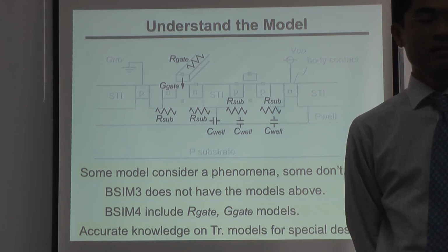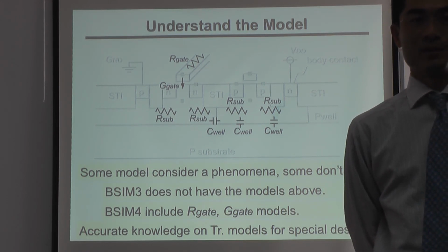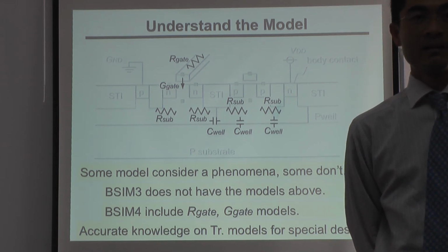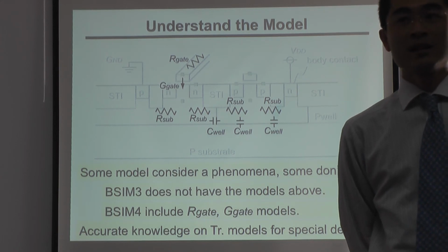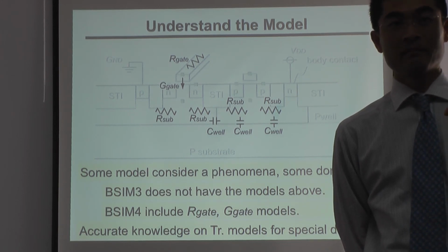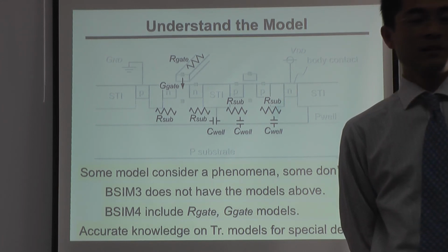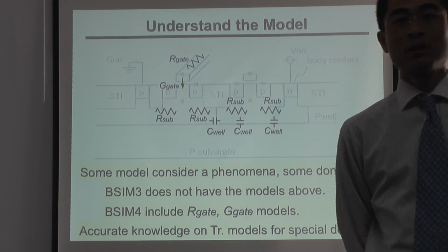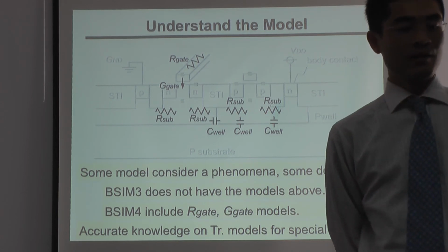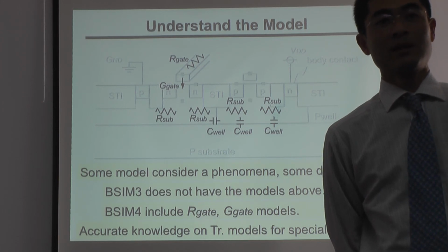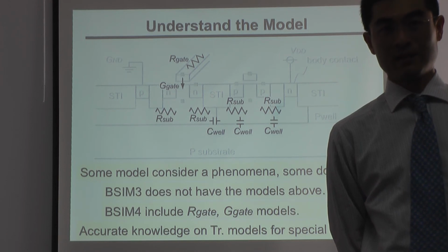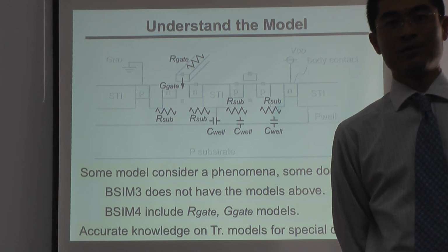That means most of the time it is on standby mode. The circuit does not operate, but the gate voltage is applied. So once we ignore the leakage current, that means the standby mode does not consume any power. But once we consider the leakage, the standby mode always has current from VDD to ground. That means the battery is consumed.